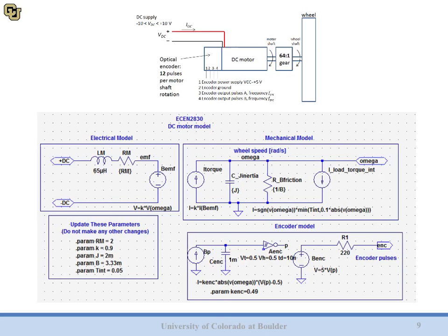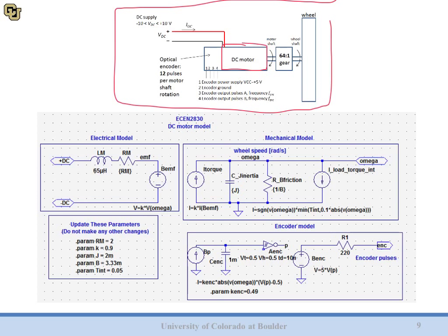And once we've figured that out, we can go back to our full model of the motor, and you can see we now know all the parameters in here. We know directly how VDC relates to motion on the gear shaft. And additionally, we now know how motion on our gear shaft relates to our optical encoder. So we now know all the parameters to relate input voltage to the frequency read on our encoder.